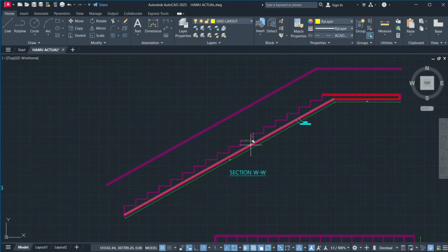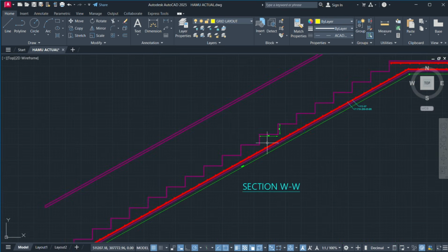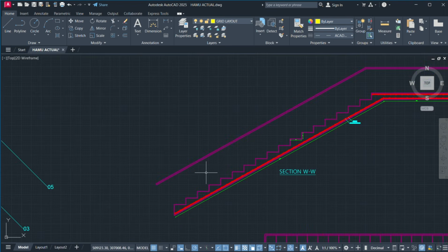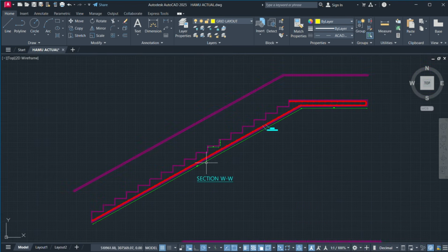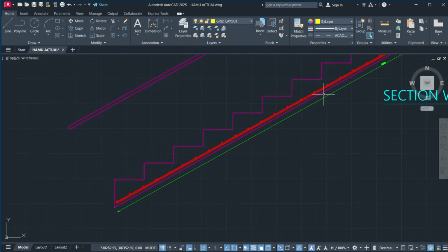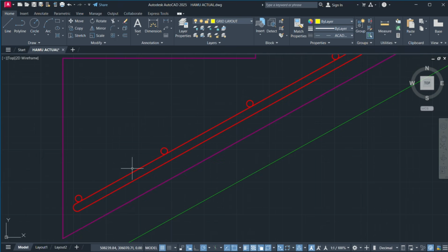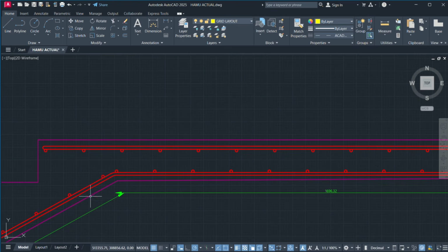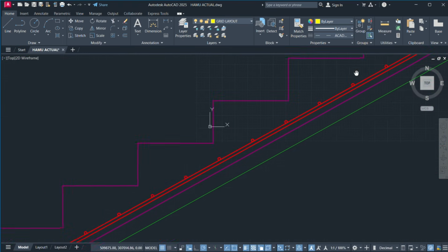Then on the stairs, you're supposed to find how many stairs are going to be needed for a particular house. So if it's a 3-meter house, you're going to have a staircase with close to about 18 risers, these steps that you actually step on. Now, the most fundamental thing is knowing how to draw this reinforcement. This reinforcement is just going to run from the bottom here, which is going to be a Y12 reinforcement. So this diameter from here to this line, which is 12, it's just going to run through all the way up to this landing. Again, you run it through.